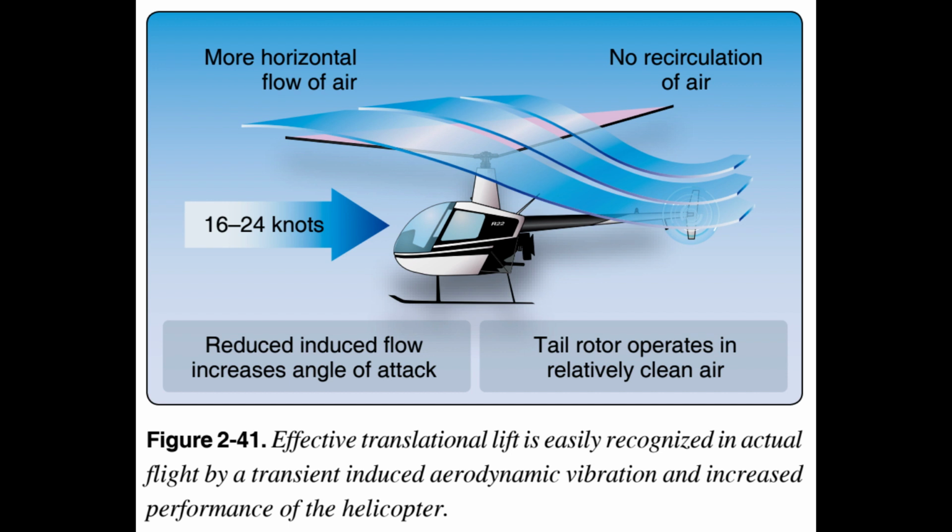This increased efficiency continues with increased airspeed until the best climb airspeed is reached and total drag is at its lowest point. As speed increases, translational lift becomes more effective, the nose rises or pitches up, and the aircraft rolls to the right. The combined effects of dissymmetry of lift, gyroscopic precession, and transverse flow effect cause this tendency. It is important to understand these effects and anticipate correcting for them. Once the helicopter is transitioning through ETL, the pilot needs to apply forward and left lateral cyclic input to maintain a constant rotor disc attitude.